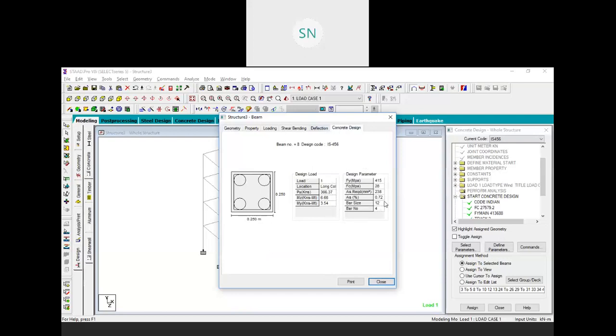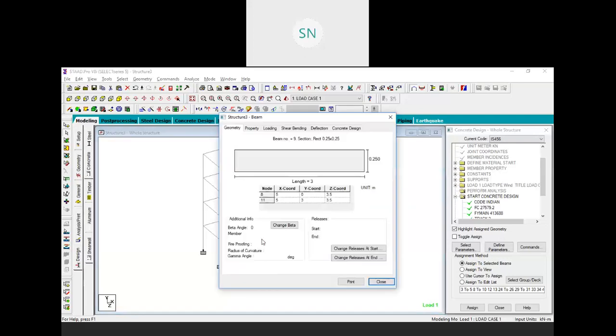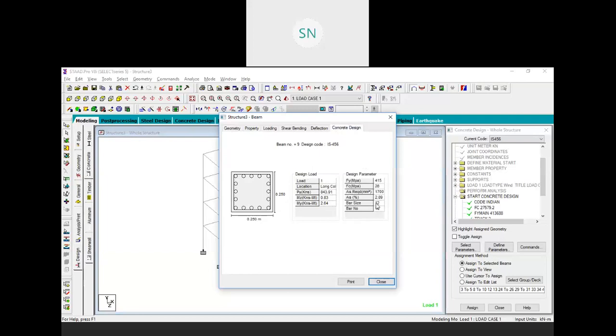Here the percentage of steel is again the same, but on this column it's increased, see, 2.83%, and the suggestion is using 12 mm diameter, 16 members for this column. So for example, this column is not economical for me. For example, I have to maintain my percentage of steel from 0.5 to 1.7%, right? Or 1.6%. So this is above my limit, right? So what we need to do is increase the column size of this one.